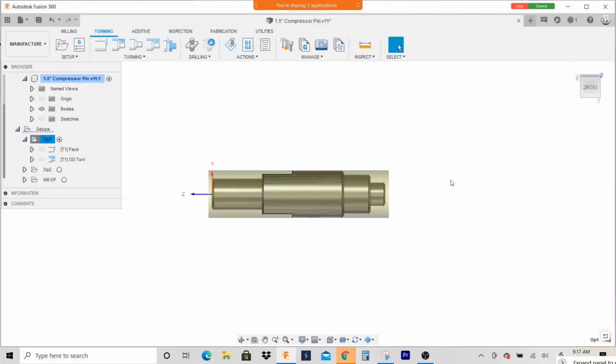I made some, I call them G code templates, and basically they're on the machine. Like the first 5 programs on the lathe, one's a stock out program, and all it does is move the tool over and stop with M00. Ideally what you do is you pull the material out against the stop, and you retighten the chuck, and when you hit cycle start, the spindle doesn't turn on or anything, it just backs up and moves out of the way.